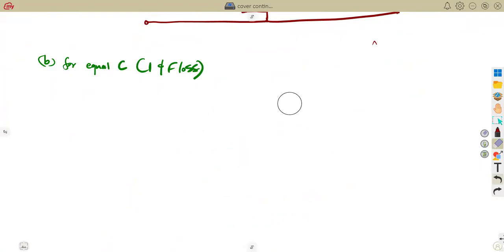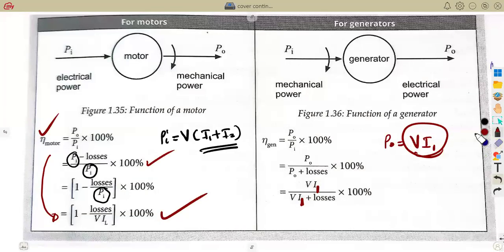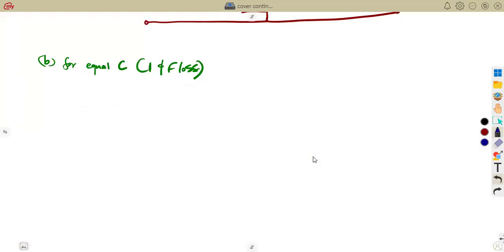So once you know these formulas, you saw the losses that we are talking about. These are the three losses I mentioned that you need to apply: the shunt field copper loss, the armature copper loss, and that part of the iron, friction and windage losses. So those are the losses you need. All right, so guys, these are like follow-up steps. On this part, please just follow up here.